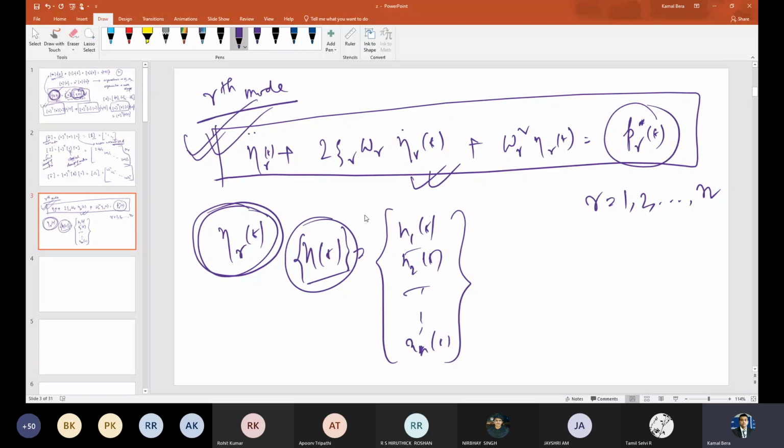And then we discussed how to formulate the equation of motion using Lagrange approaches. We also talked about that at the starting, but we mainly concentrated on Newton's law or D'Alembert's principle, by drawing the free body diagrams of each mass and then writing the equilibrium equation. Here that is not required. In the Lagrange approach you have to find out the kinetic and potential energy of the whole system, then apply the Lagrange equation, which comes from Hamilton's principle.